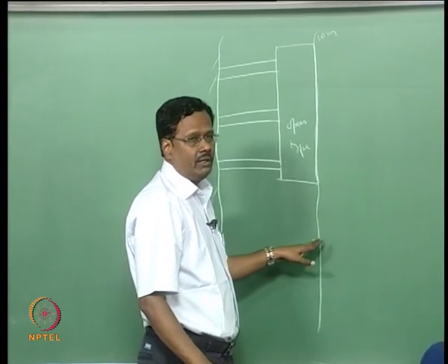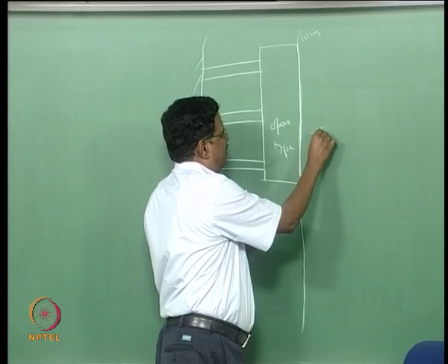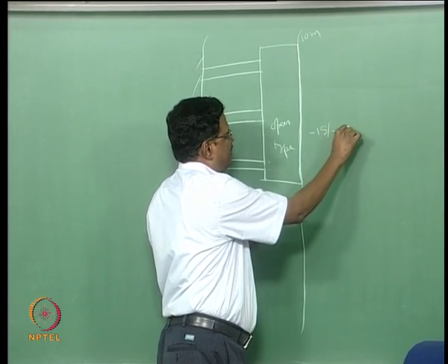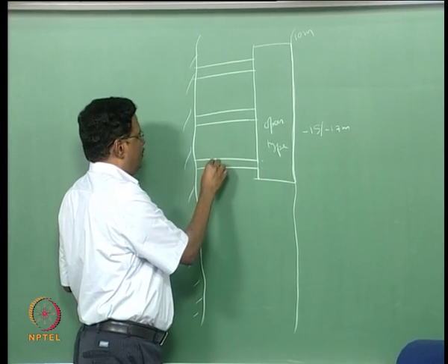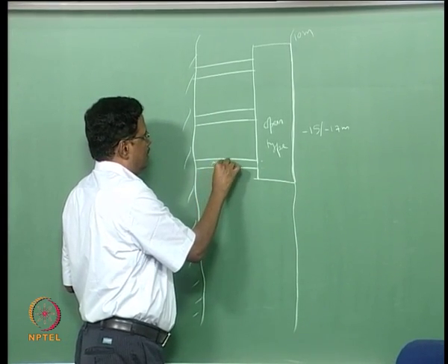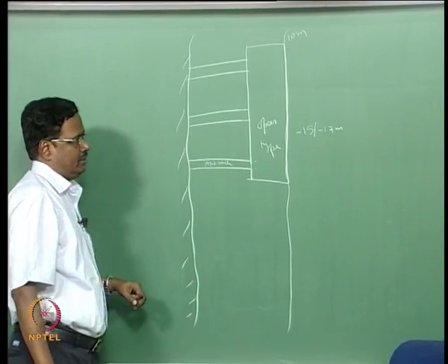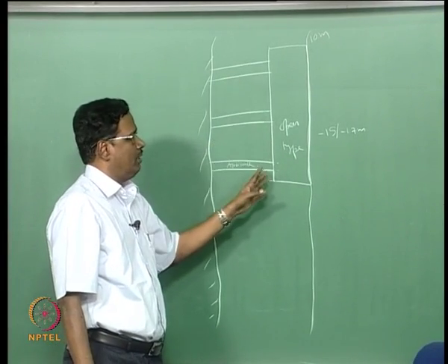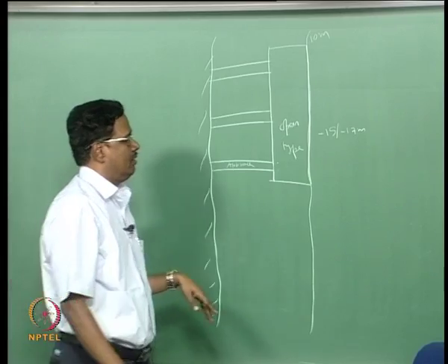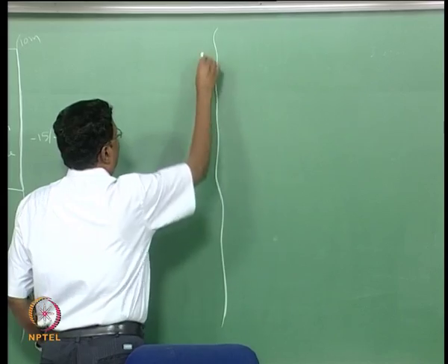Here you will have 10-meter water depth and you can dredge this area to minus 15 meter afterwards, or minus 15 or minus 17 meters. There is no diaphragm wall, it is an open pile structure. There will be an approach and then you can construct the structure. This is a structure in which there is no diaphragm wall, there is no continuous wall which is retaining the soil.